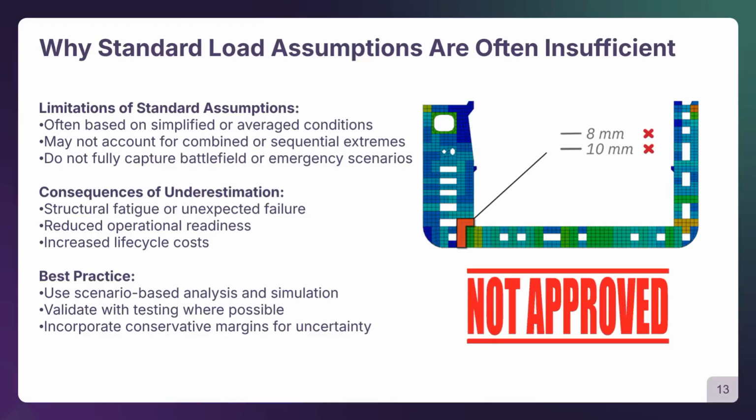Here, the best practice would be to use scenario-based analysis and simulation, taking also experience from another structure which already operates, and trying to simulate these loads as accurately as possible. And if possible, validate them also with testing. All these assumptions should be taken with conservative margins.